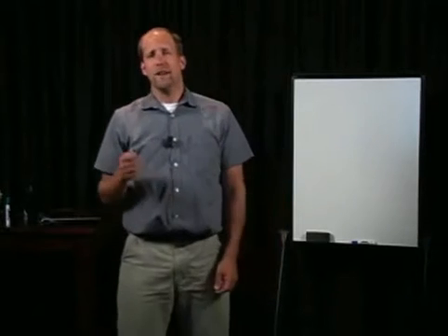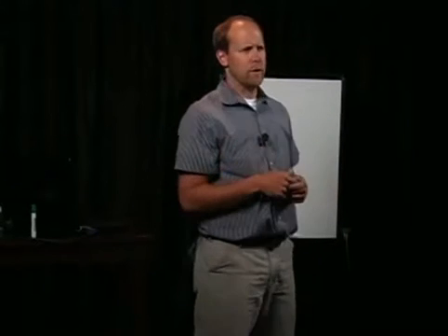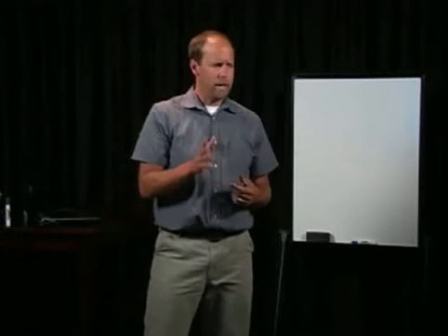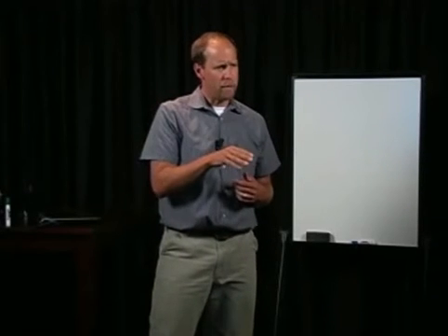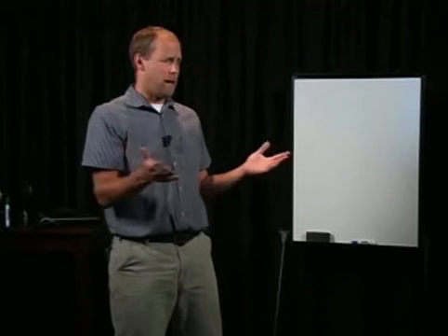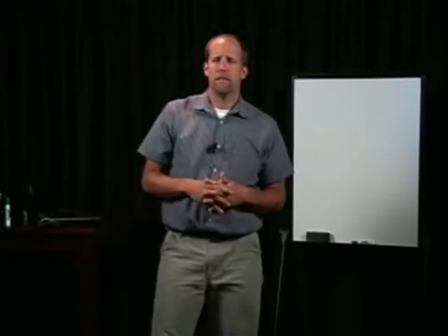A non-contact voltage detector, a beeper instrument that goes off if it detects voltage. It doesn't help you detect moisture, but it keeps you safe because you will be put in positions where some electrical wires may be hazardous to your health. A work light. If you're going to use a work light in any kind of damp area, like a detached garage with a dirt floor or a crawl space, make sure you have GFCI protection.